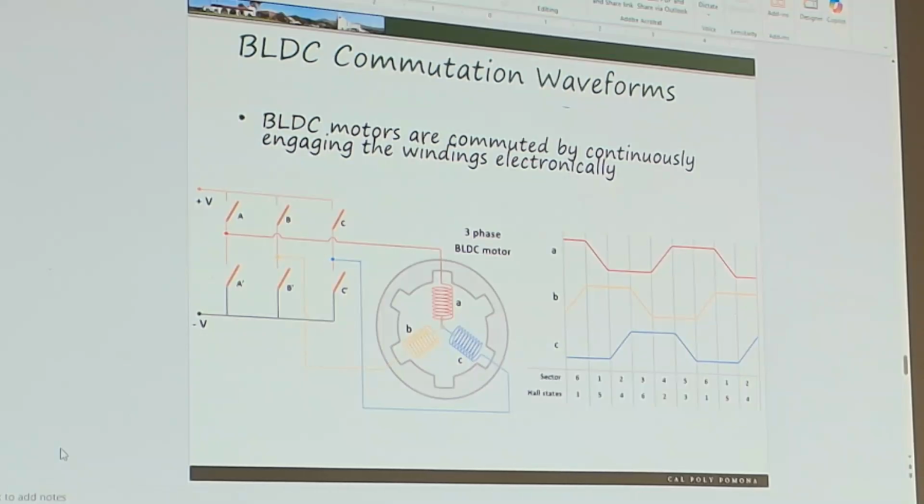So we can do a full PID on each current into each winding. And you have 3 currents simultaneously being controlled. You have 3 PIDs simultaneously being controlled. You're controlling the voltages and currents into those windings for a given position based on what your feedback current is being measured at, as well as potentially an encoder. So you see where we're at. BLDC can get really complicated really fast. Even doing the simple stuff isn't simple.